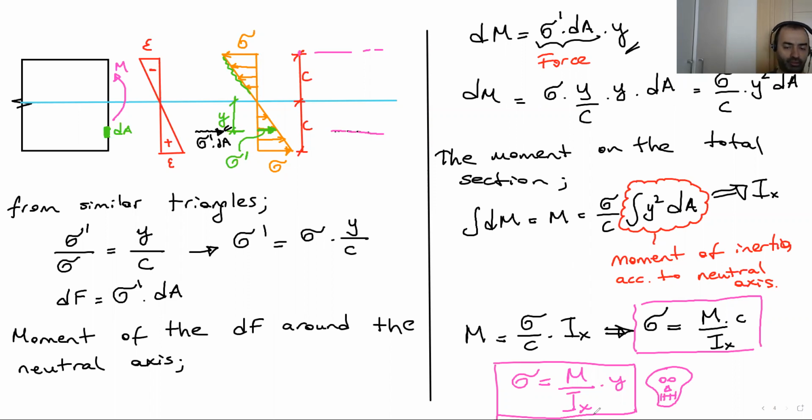Generally with this equation, you can calculate the stress wherever you want. What we generally do is calculate the maximum stresses. We deal with the maximum stresses at the top and the bottom edge. So instead of y, we are going to put c.